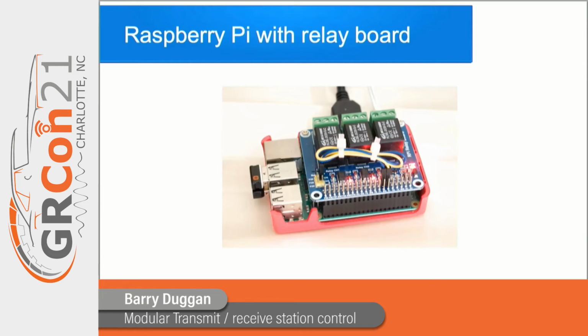There are actually jumpers on this block right here, but they use some pins that are dedicated to other functions. And I wanted to use pins that had no dedicated function. So I pulled the jumpers off this block and put in the wires to pick up the pins I wanted.